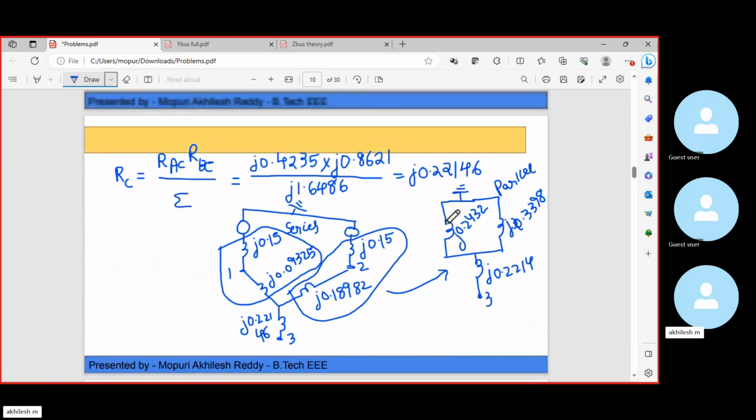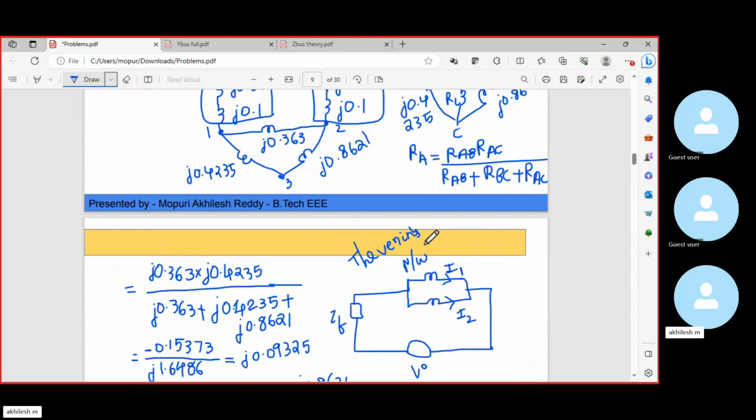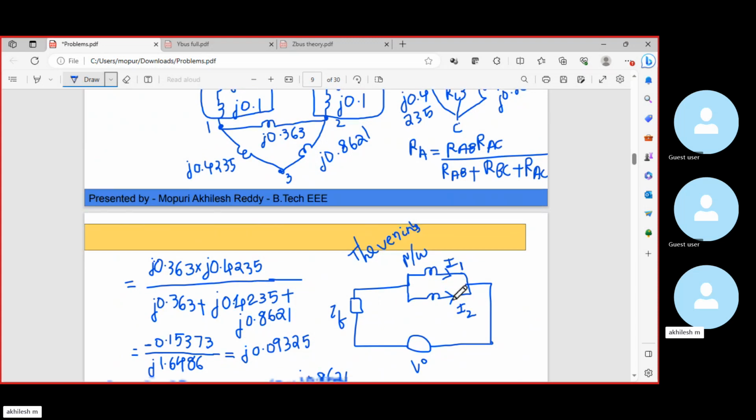The circuit will always have two parallel branches. The current flowing through the parallel branches should be from the synchronous machines. If there is one synchronous generator and one synchronous motor, then one branch will take the current from the generator and the other branch from the motor. If both are synchronous generators, each branch will take the current of a generator, as in this case.